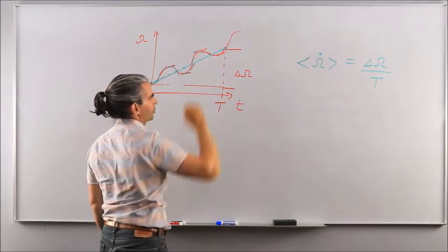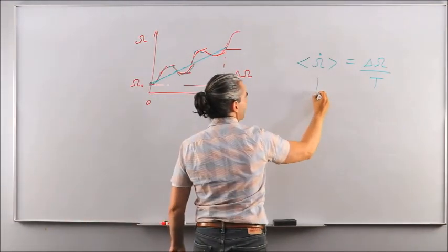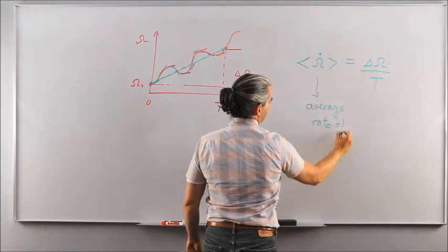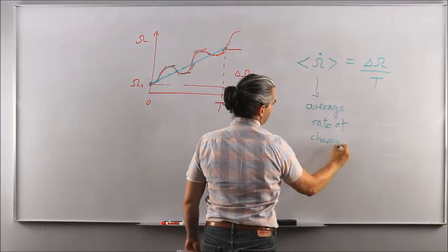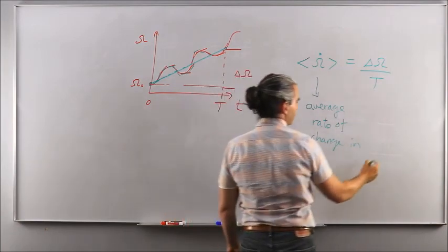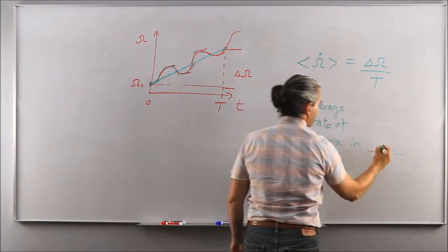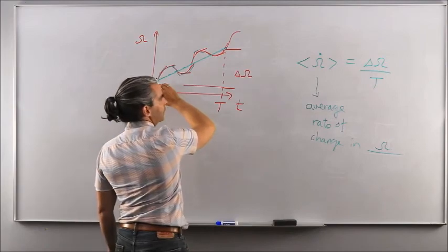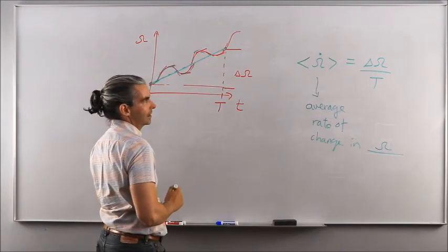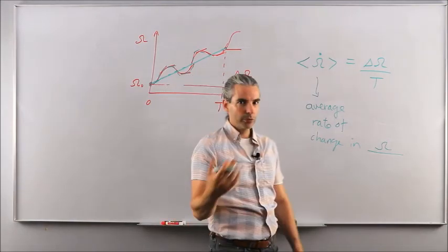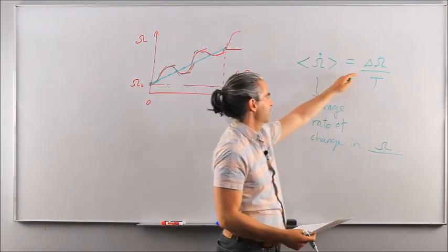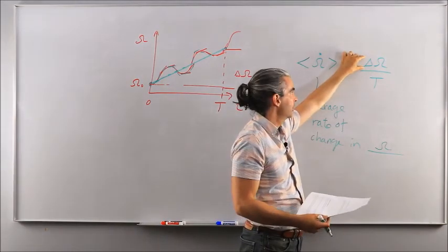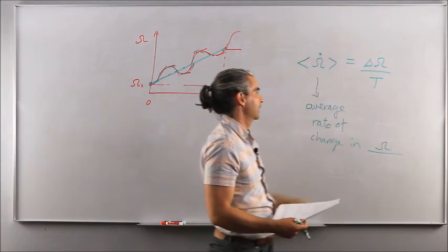So you just draw a straight line and you call it the average rate of change, and you fill the blank with the orbital element in question. In that case, this is inclination, okay? Just don't forget that this is always calculated over 1 orbital period exactly, and not half an orbital period or 2 orbital periods. By default, it is always a secular variation, which is the net change after 1 orbital period divided by 1 orbital period in seconds, okay?